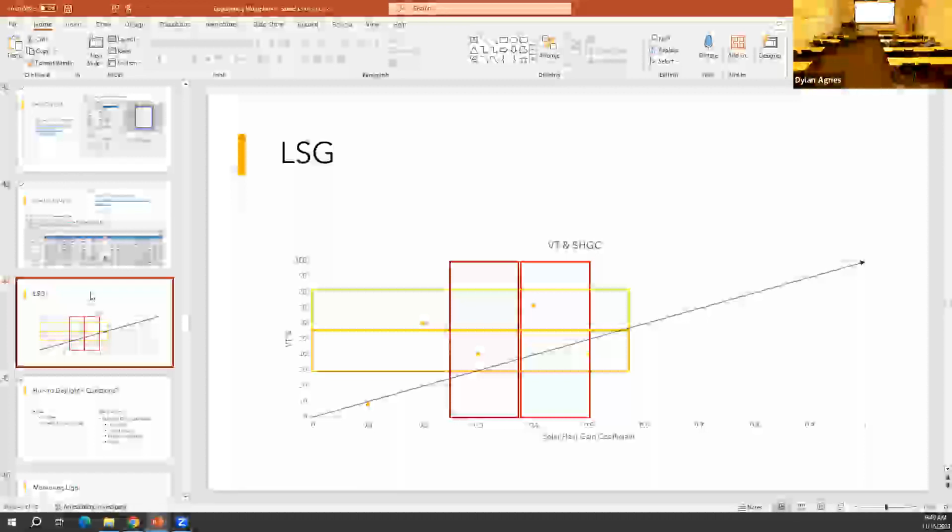So if you do want the solar heat gain, you would do that, and you would also reduce your U value, the U factor, a little bit, not by too much, because you still want to be in compliance and you still want to have a decent building envelope. But you reduce it a little bit so that you could allow that extra solar heat gain to come through. Do you see people designing buildings to take advantage of that, or is this fairly new?